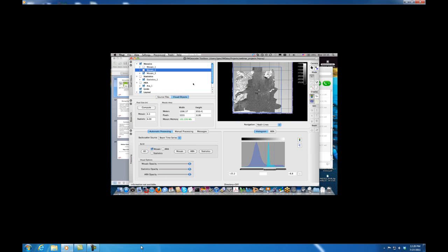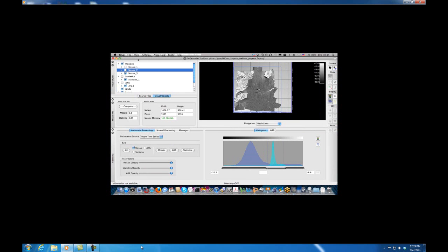So what we can do within GT is say, okay, I've already done the bathymetry processing when I ran CUBE, and I edited the soundings out of that. I accepted the CUBE surface and edited all the soundings out of the PFM file. I can actually use those now within GT. So every ping and beam that was deleted as noise or as one of the fish traps, I cannot use in the backscatter processing.